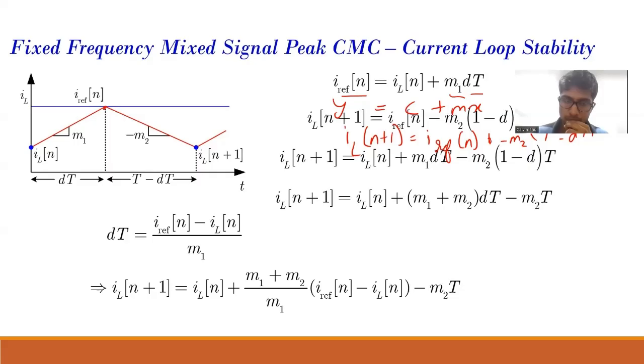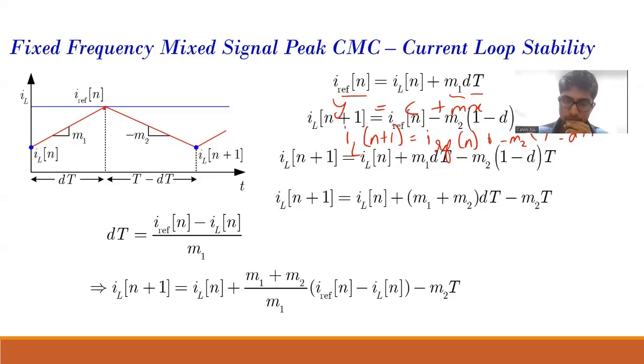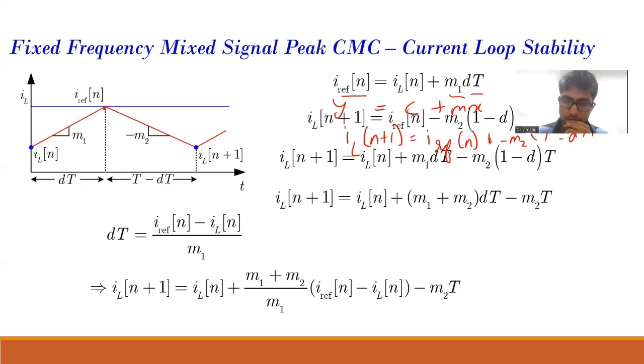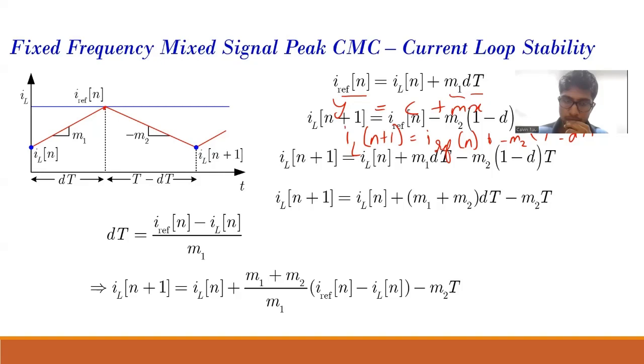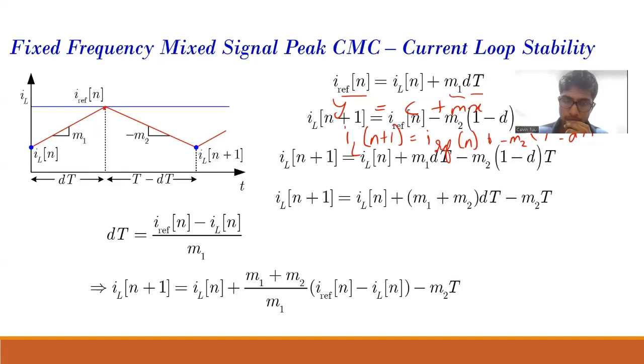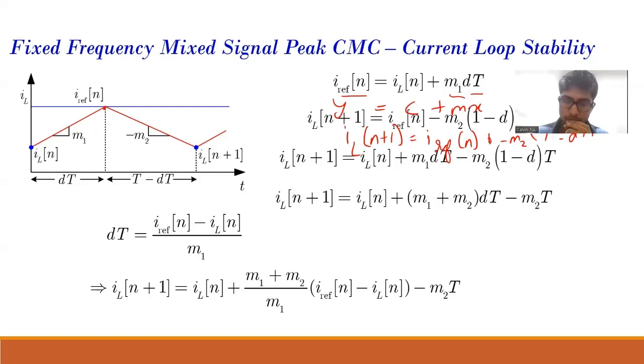Okay, yes. In this case, we have not considered the noise which could happen. I give the set pulse over here. If I give the set pulse, my switch should turn on, and once the reset pulse comes, it should turn off. But what if the set pulse and the reset pulse come at the same time? Then the switch will not turn on; it will continue remaining off, and that will result in the voltage fully dipping. So to prevent that, once we give the set pulse,